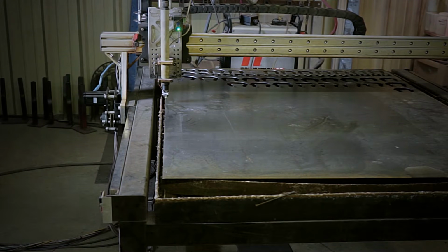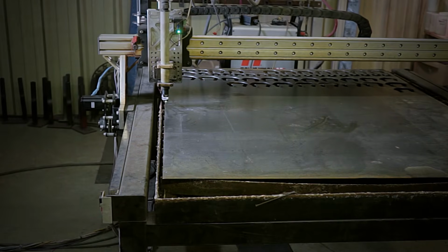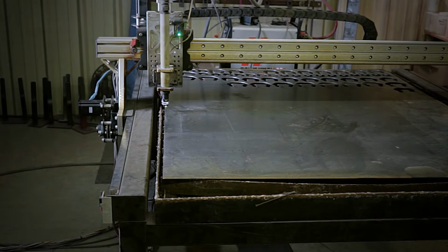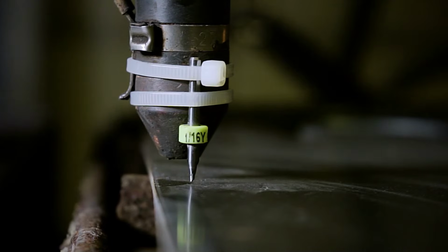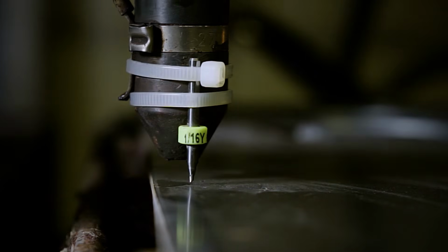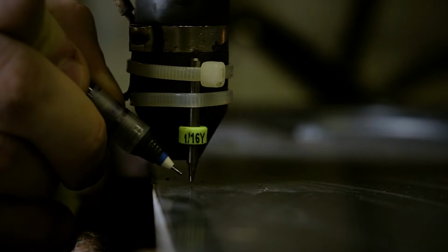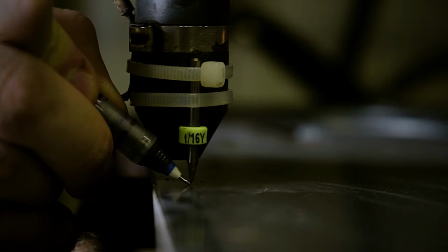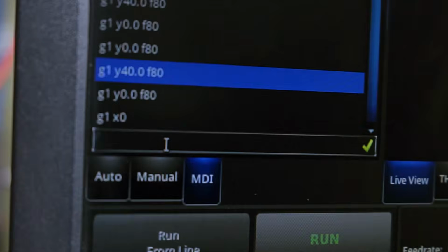For the following steps, make sure your machine is in E-stop before continuing, otherwise you may get seriously injured. On your plasma table, remove the torch and either mount a laser or sharp-pointed tool in its place, or mount this beside the torch. Move this to a point on your table that you can mark as a reference point for measuring. Mark the spot as precisely as possible.